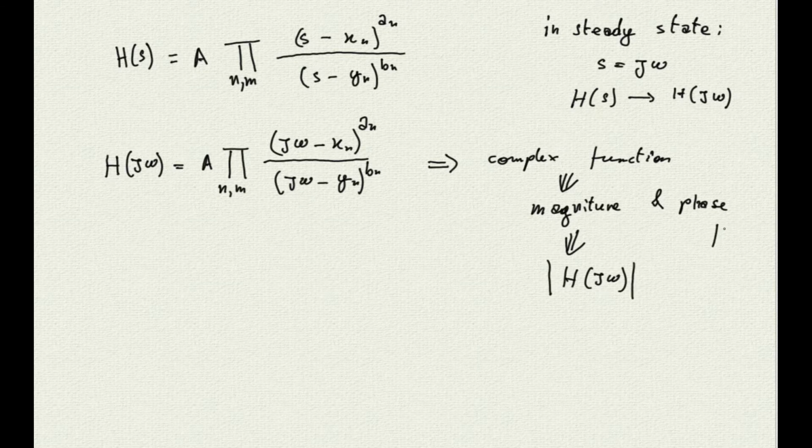The phase is the angle at a particular time on that circle we previously mentioned, where we travel at the omega speed. This angle is simply the arctangent of the ratio between the imaginary and the real parts of the transfer function. Yes, I am also using trigonometry now, but please be a little more patient. I had to say it to explain what we are doing, but that's about all I am saying about math.